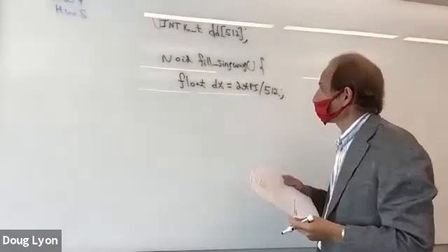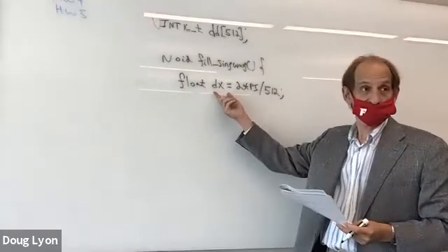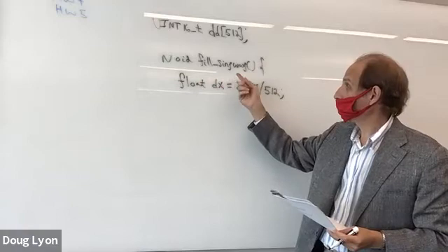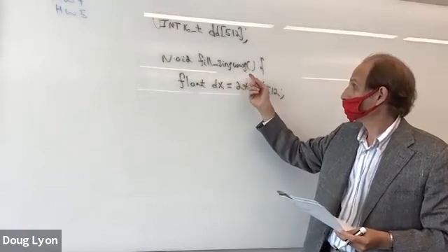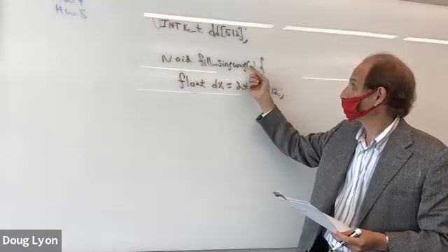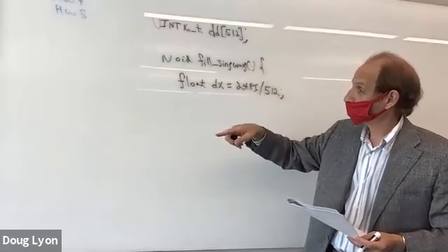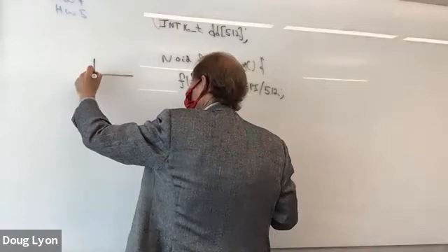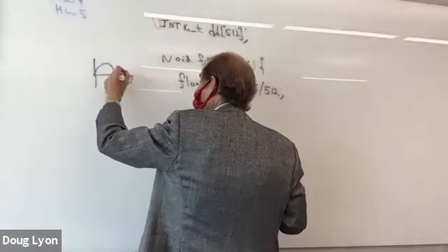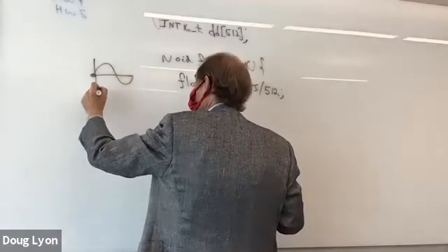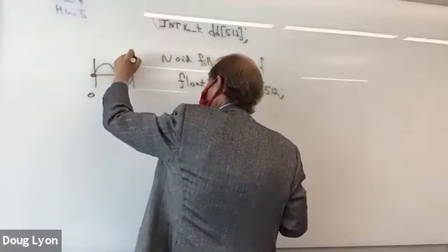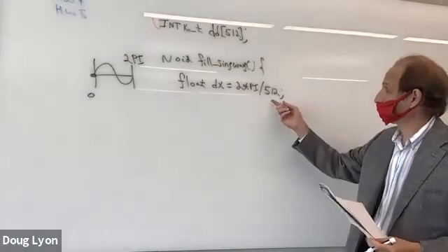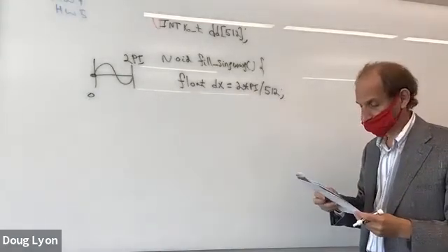And what that does is it'll allow us to increment theta by 512 times and make sure that we have a theta that is actually going to essentially move the sine wave from the beginning of the cycle to the end. So this will be theta is 0, and here's theta at 2 pi. And we'll go in 2 pi divided by 512 increments.